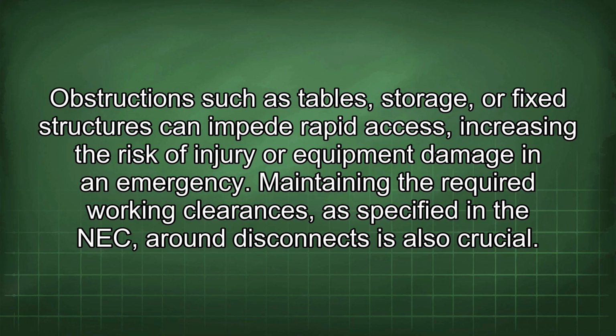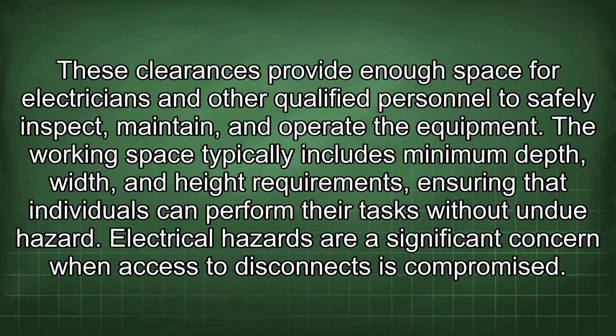Obstructions such as tables, storage, or fixed structures can impede rapid access, increasing the risk of injury or equipment damage in an emergency. Maintaining the required working clearances, as specified in the NEC, around disconnects is also crucial. These clearances provide enough space for electricians and other qualified personnel to safely inspect, maintain, and operate the equipment.